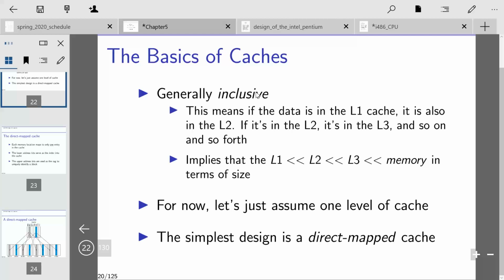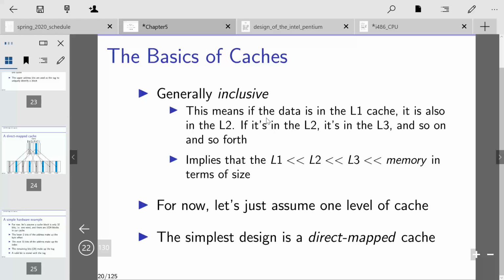But anyway, when you pull in a cache line, you oftentimes have to replace the cache line that's already there, and this relates to placement, which we're going to talk about in a second. We use the term evict a cache line, and so the victim cache simply stores evicted cache lines. By its natural definition, it is an exclusive cache, and it provides quite a performance benefit. I'll circle back to victim caching after we've talked a little bit more about how level 1 inclusive caches work.